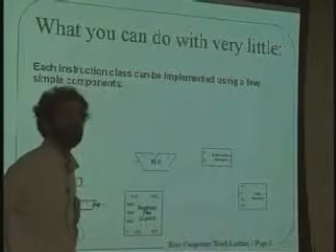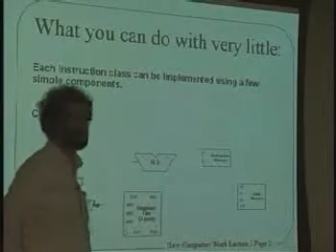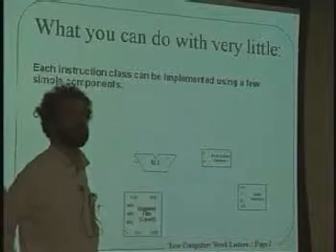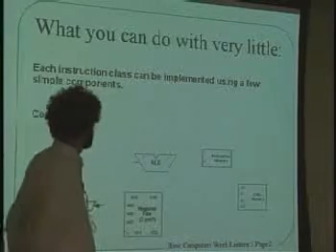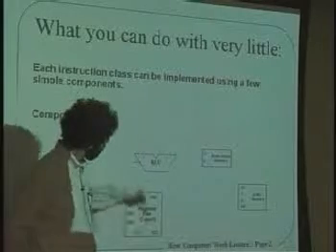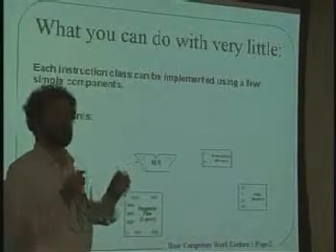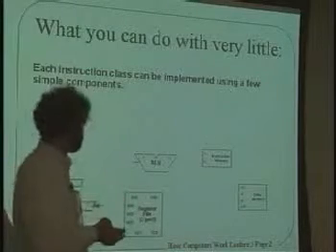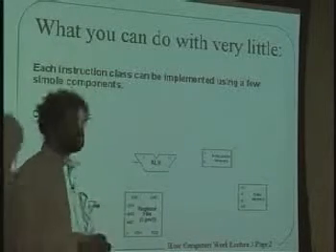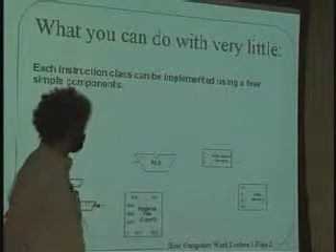And then we're going to have something called the register file, and guess what this is going to be used for? For holding registers 0 through 31. Except in the case of register 31, it'll have a pretty easy time because it just throws out the bits and produces a 0. But that register file is going to have two paths for doing reads, because we'll want to read two registers at the same time to combine them in some kind of operation, and one path for doing a write, which is going to be used to write the result back to one of the other registers.